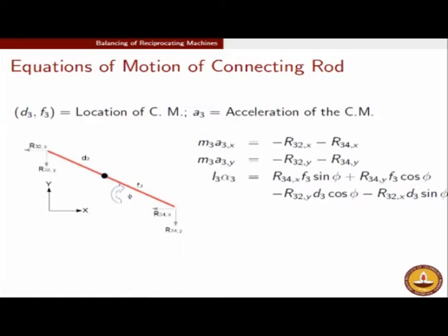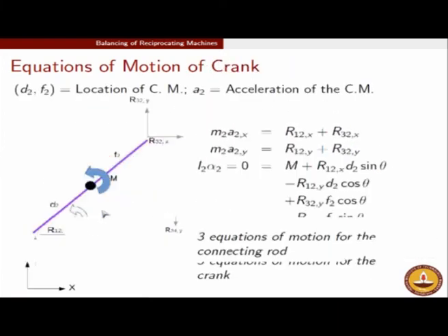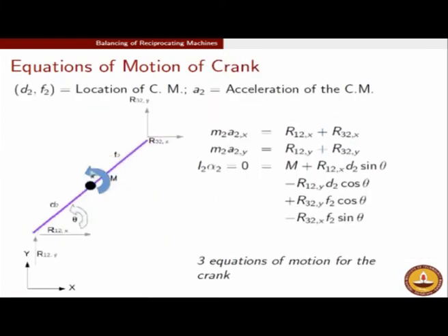So we are discussing the analysis when our engine speed is constant. We are not discussing in this talk what is happening when the engine is accelerating. We are now discussing the situation where the engine has a constant angular speed. In order to have a constant angular speed, obviously you must apply a certain amount of torque. You are right in saying that the reaction forces are varying in time, but this moment could also vary in time such that the total moment is 0, and that is exactly what we are trying to enforce through this condition.